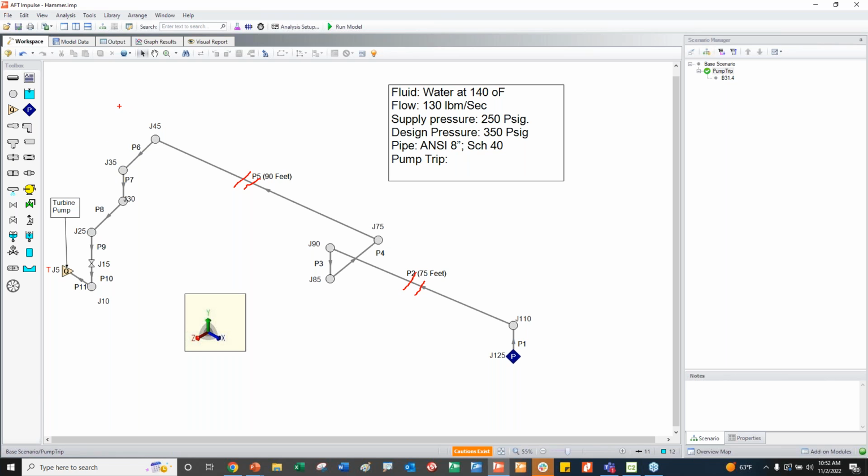But if I have a hanger here, I would like to examine this section here, because it might cause problems. This section might have very low frequencies, and because it has a hanger, and a hanger is not a dynamic restraint, it depends on the arrangement you have. But in this example, we picked these two long ones because generally, as I said, these are the longest ones.